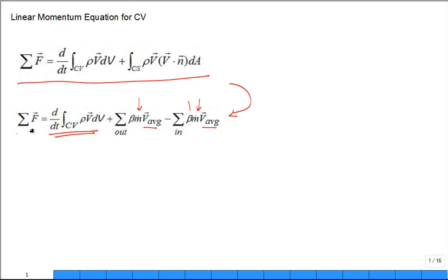And then these are the forces. And remember, always take a look at body force. Do I have gravity? Do I have weight? Is that important? I need to include it. Second one, any normal surface forces, any pressures. Is the pressure on this side of the control volume high, that side low? And then also some shear forces. Some problems will have that viscous shear force at the boundary, and you need to consider that.